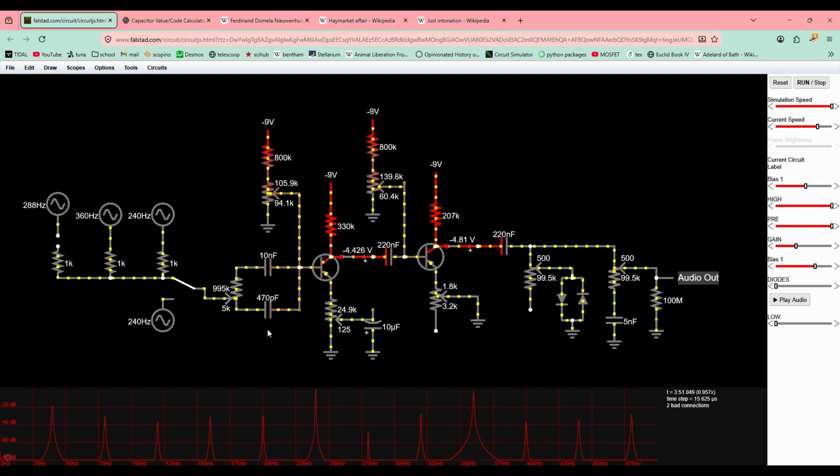So I also had the idea of putting the diodes on a variable resistor, so you can kind of choose how much you want the diodes to be able to steal. But I also don't like this, for the same reason as this one, these variable effects are just difficult to make work correctly. In the end, I also added in this low pass filter.